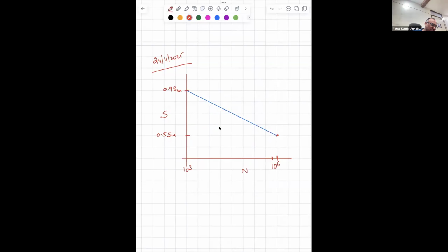So this is the scenario when sigma m is 0. This S is also nothing but stress amplitude. Either S or sigma A, both of them can be used interchangeably. These values 0.9 SUT and 0.5 SUT correspond to sigma m equal to 0. Is that clear? Yes, sir.